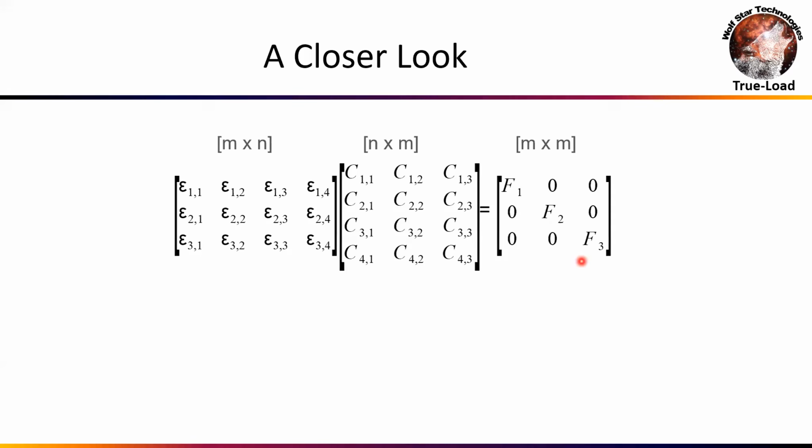If we went off and collected the strain data and went through the process with TrueLoad, TrueLoad would essentially be doing what's called a Craig-Bampton analysis. A Craig-Bampton analysis calculates the flexible body response along with the ground interactions from the unit displacements at the boundary conditions. So we get a complete characterization of the dynamics just from a bunch of strain gauges. It's a pretty incredible technique that you can get that level of understanding about your parts with just some strain gauge measurements. Okay.